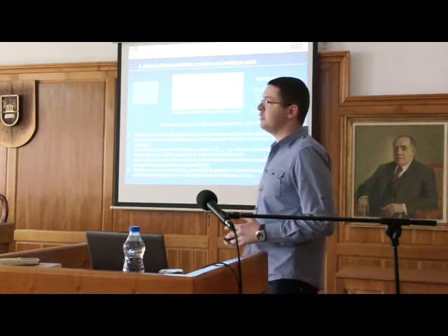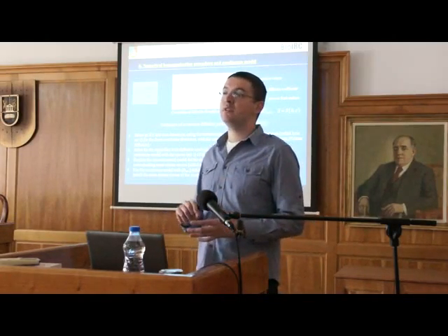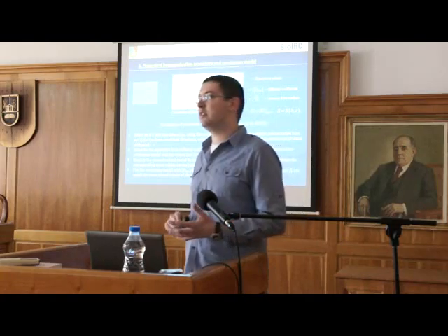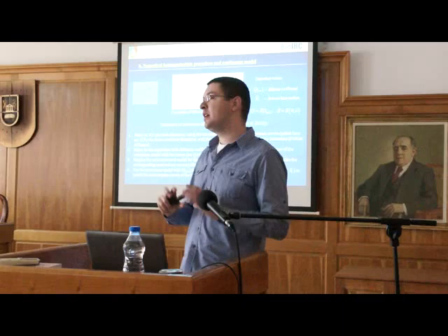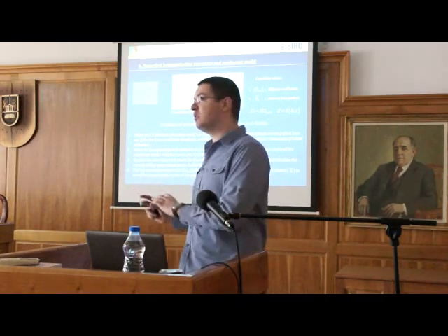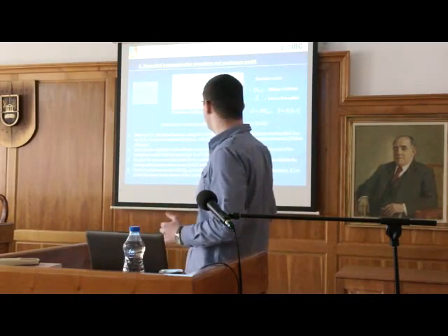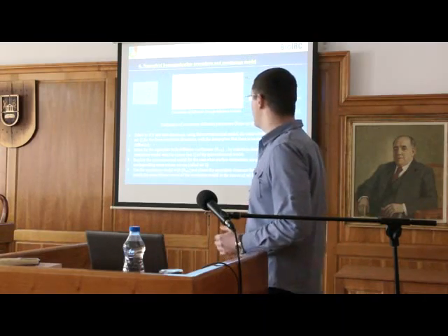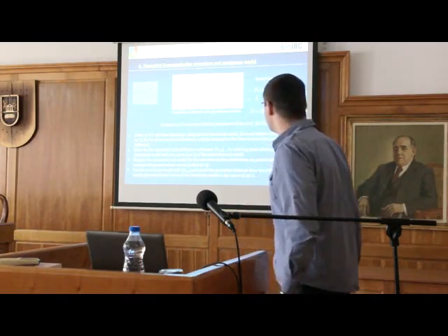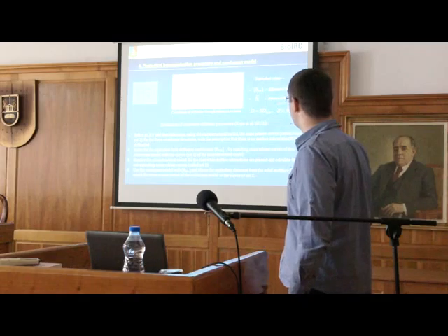For us, it is very good because if you want to model a microstructural model, we need a lot of finite elements inside that reference volume. If we replace this microstructural model with a continuum model, we replace, for example, 1000 equations with 2 or 8, because we have just 8 nodes for this finite element. So we introduced these procedures, which are used for calculating these equivalent values.